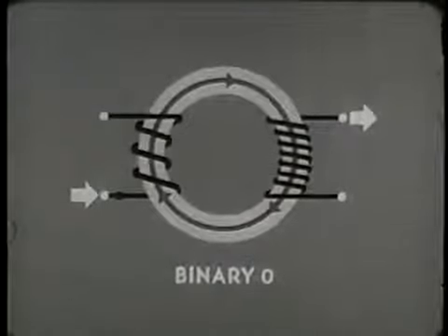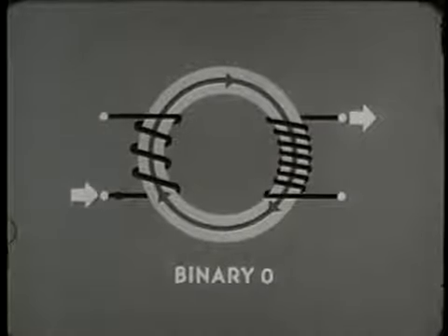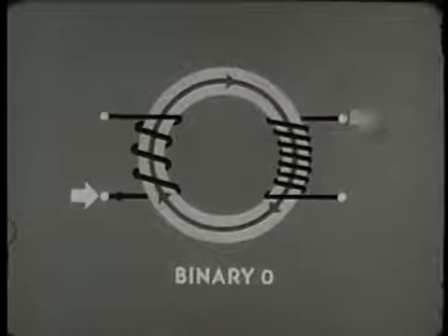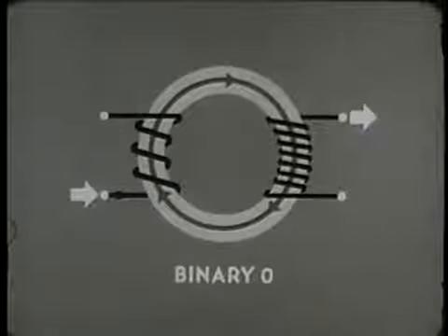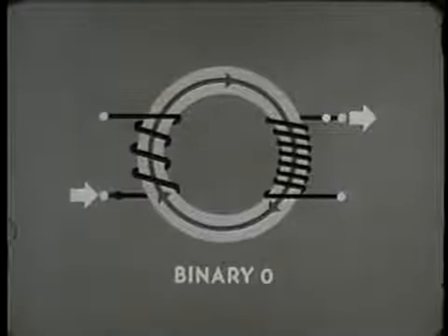The way these two conductors are wound, a pulse of current sent into the bottom of the input winding results in a pulse of current going out of the top of the output winding. We used a dot to keep track of the polarity of the input winding, and a similar dot will establish the polarity of the output winding. This gives us another rule about the dots in a magnetic core diagram.